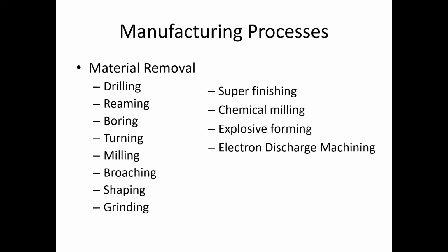Shaping and grinding. There's a tool called a shaper, and I'm going to lump these two together. This is not your bench grinder that you're thinking of, or your angle grinder that you may have in the garage. These are very precise tools, and they're both very similar. The material will fit on a magnetic base, and the base travels very precisely in uniform strokes to an abrasive, and it takes it to a very, very high precision finish, both smoothness and dimensional tolerances.